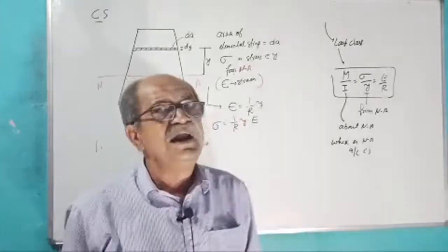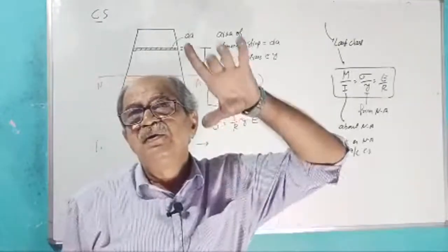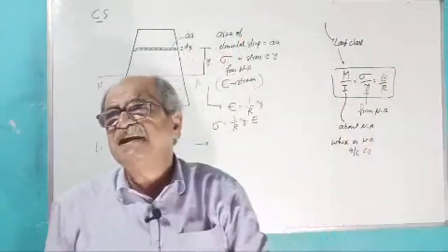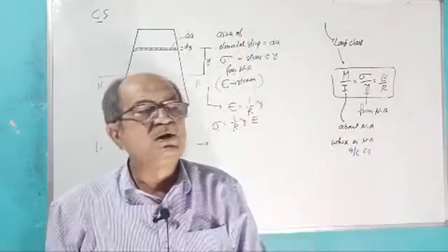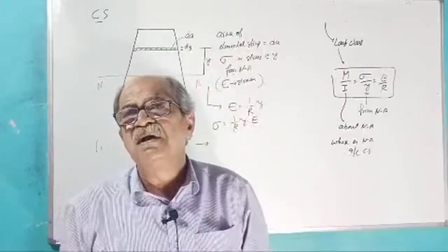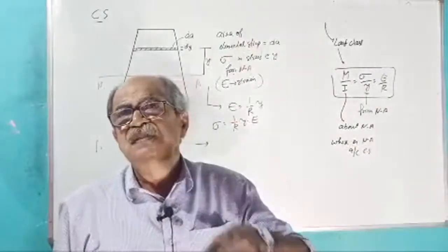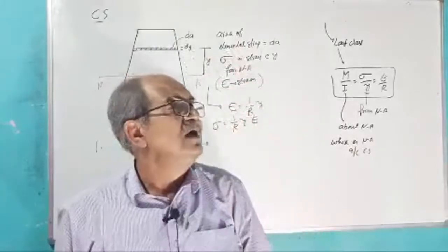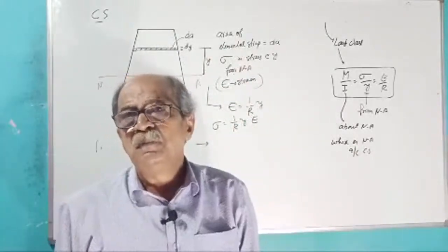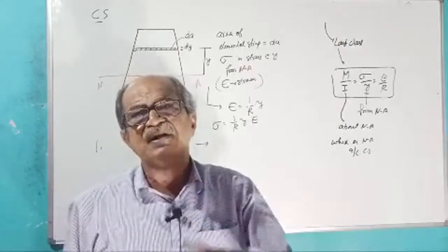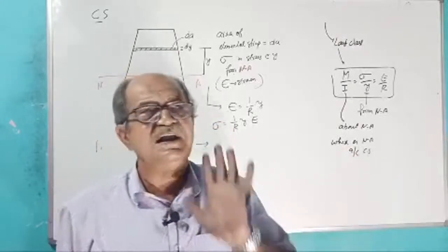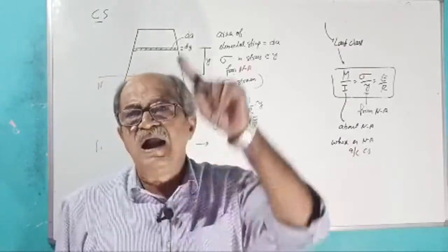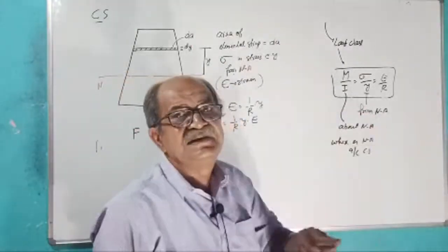In pre-stressed concrete, if you consider bending moment and the bending moment due to eccentricity independently, the neutral axis will be through the CG. But when you consider the resultant stress diagram with the axial force, that neutral axis will shift from the centroid. That shift will be equal to bending moment divided by P. You study all that in pre-stressed concrete. One pressure line and force line concept is there, so at that time this information is required for you.